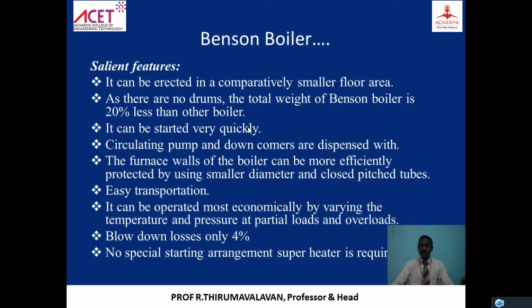No special starting arrangement. A superheater is required. Directly this one pipe is passing. So the same water is circulated in and around. So a separate superheater is not required. In other boilers, first we have to initially start with some superheated steam in the initial stage. Then we have to circulate the steam again. Right? But in Benson boiler, the same water is going, no need of a separate heater and other things.